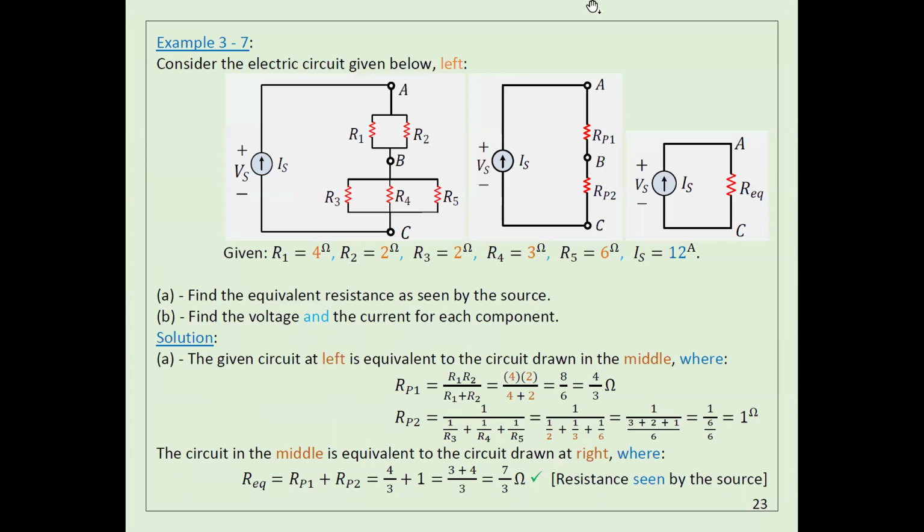By the way, I can figure it out from here. Look here, guys. The current is coming this way, it's going to split and will come here. The same current will be here. So the current here will be the same current here. So this resistor and this resistor are in series to each other. The voltage here is equal to the voltage across these two, which are equal. So the voltage here and the voltage here is the same voltage, but the total voltage is actually going to be split between these two and between these two. Any questions?